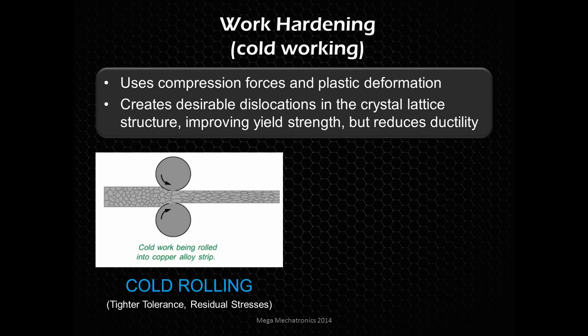If you go buying materials, cold rolling, you could see that material entering between rollers that's exaggerated. There's probably a series of rollers that gradually get smaller and smaller, but you see how those grains are affected. They're elongated and stretched out. Most of the time it gives the material tighter tolerances, as opposed to a hot rolled material that might move around and change.